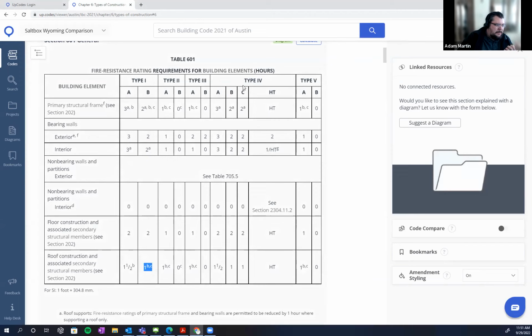So when you're thinking about mass timber as a large structure, you should be thinking about it as very analogous to concrete in its weight and its heft and what you're doing with the structure. So I think it's really fascinating for us, this combination of light framing and mass timber floors and diaphragm, and what is the benefit of that versus a purely mass timber structure, right?